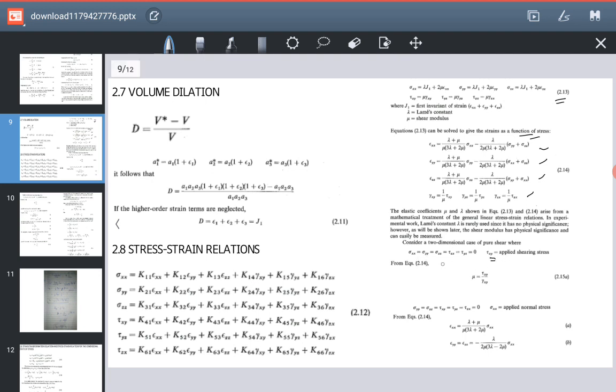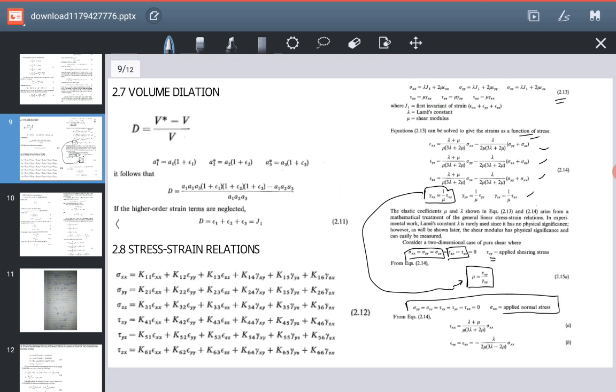in which there is only shear stress, all normal stresses are zero, and the other two shear stresses are also zero, and they have converted this into this. So it's just a different arrangement, and nothing special is being done. But in this condition, they have considered a special case of uniaxial stress, where stress is applied on just one axis, the normal stress. In this case the normal stress is sigma xx, and all other stresses are 0.